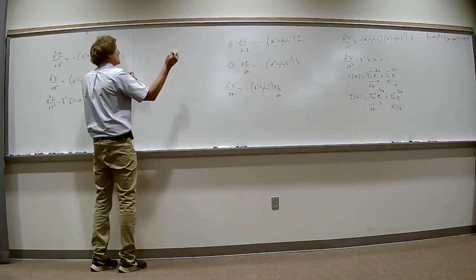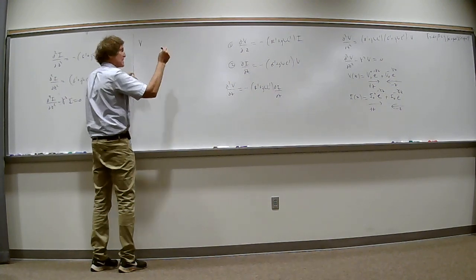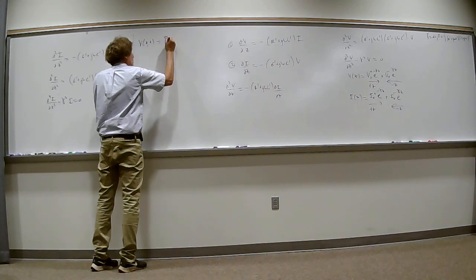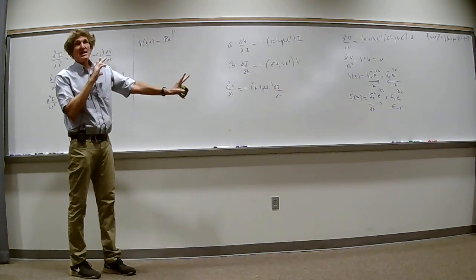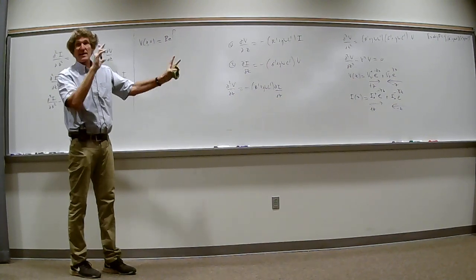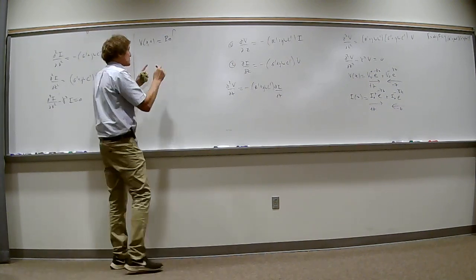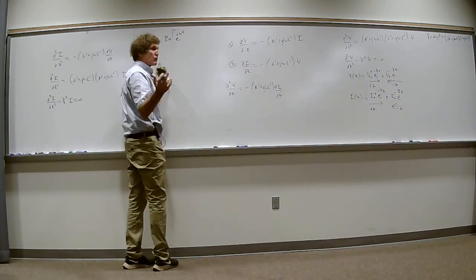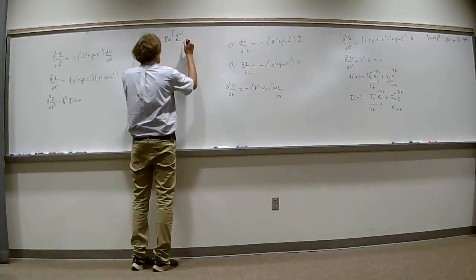All right. What he's about to say is, if I want to go to the time domain, I had the phasor domain. I say V of z,t would be the real part. Now that is just taking the real part of the quantity. If you got a j there, anything times j is neglected. Real would be like a cosine, sine, just by itself. You all follow me? So it's going to be the real part of e to the j omega t. So we're reintroducing the variance with e to the j omega t, and then it's times the phasor form.